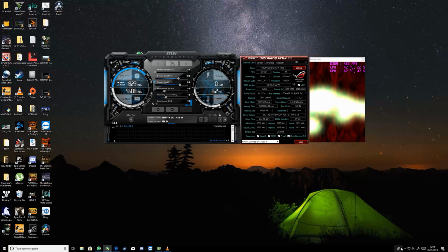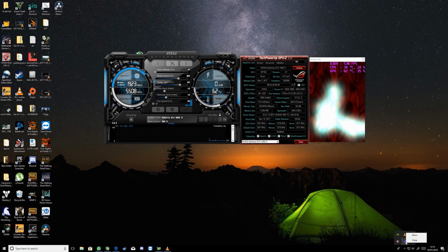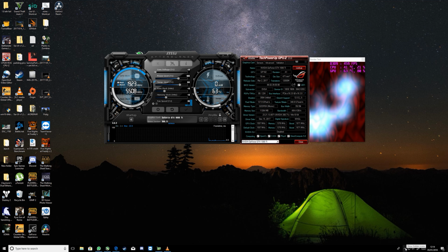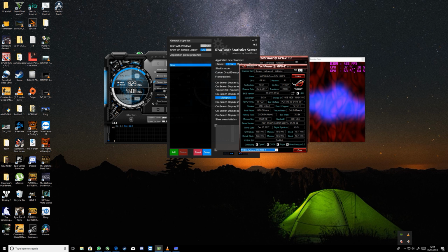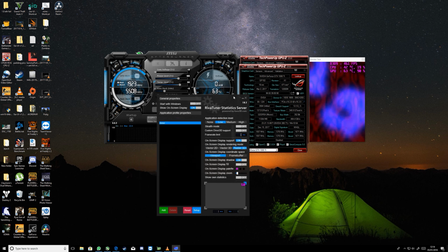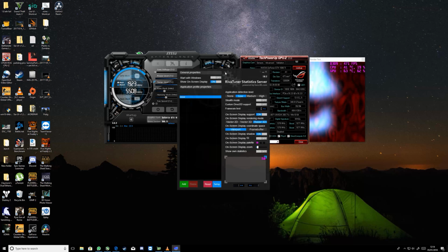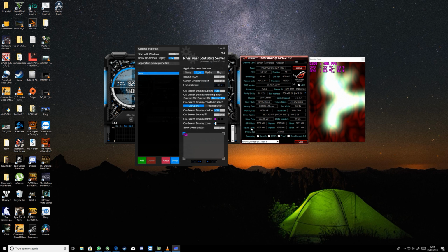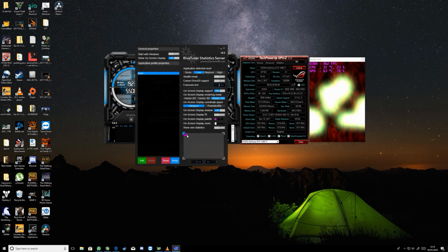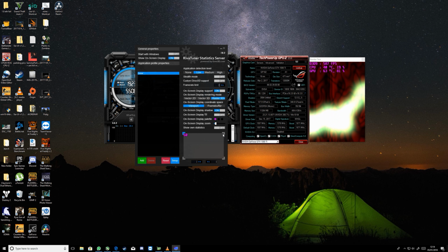Moving on to MSI Afterburner itself, this software allows you to take control of the video card's BIOS and instruct it to apply more voltage to the graphics core as well as the memory chips, and adjust the fan profiles. This allows you to increase the graphics card's core frequencies as well as the memory chip frequencies, which allows you to achieve better performance. It's also packed with a whole bunch of other neat stuff, like the ability to overlay information in games such as GPU temperature, CPU temperature, FPS, etc.